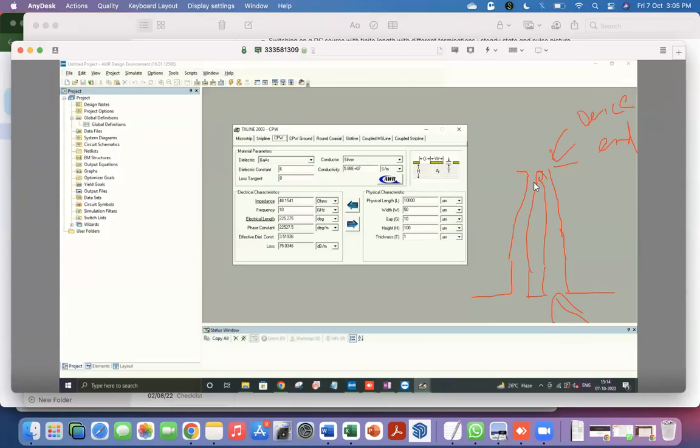Now, even microstrip allows you to do that, because there you only have to, actually, no, microstrip doesn't allow you to do that, because if you reduce the center width, there's no way to change the height, because that's the only other dimension you have. So that's why you need this other control, which the CPW allows you to do. I'll show you later on some images of such devices where you start from a very large CPW and then go down to a very narrow CPW. These kind of devices are used in our lab quite routinely. Okay.